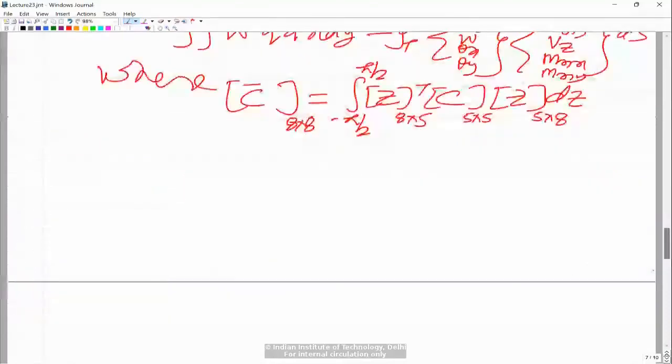So yes, once we have done this, we now have a well defined integral functional, which involves the unknowns u naught v naught w theta x and theta y, which are functions of x and y. So we will have to talk about the interpolation of these variables. When we develop the element, we obviously talk of the interpolation of the unknown variables. When we look at the displacement approximations, the primary variables are u naught v naught w theta x and theta y.